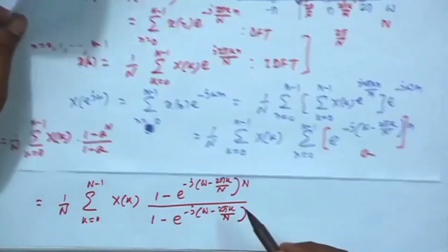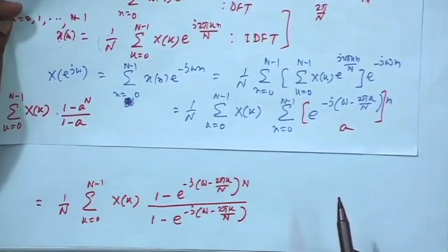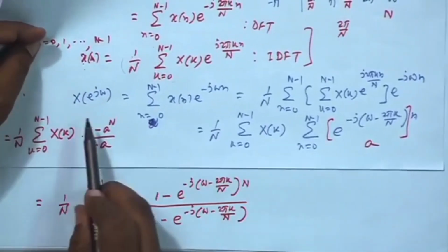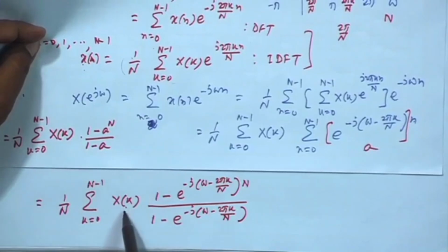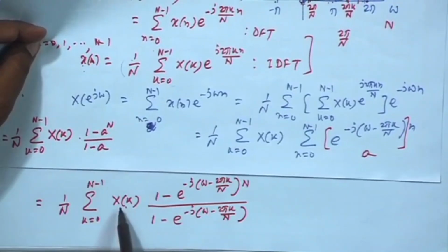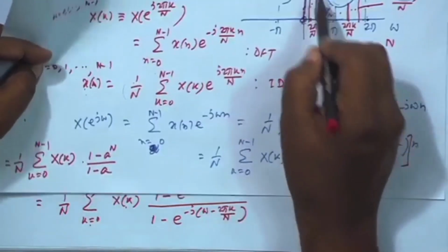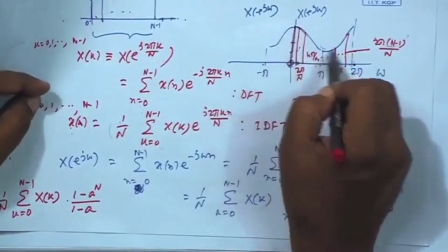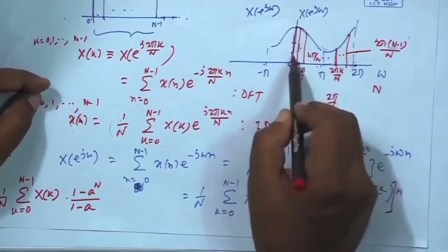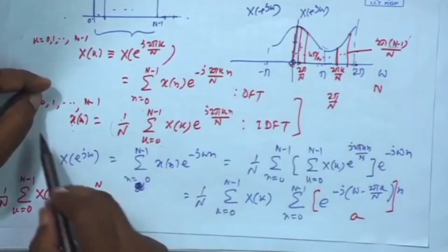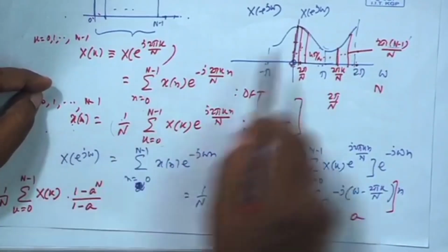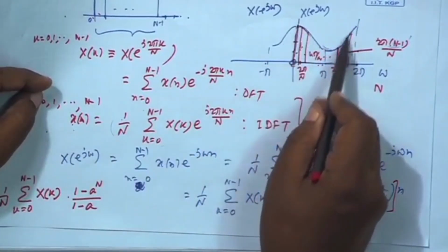Okay, a function of this kind. So, that means DTFT can be obtained from its own samples. After all, what is capital X k? k equal to 0, k equal to 1 and up to k equal to N minus 1 means you are basically taking the whole DTFT itself and sampling it. So, if you know the samples, that is this capital X k, using them you can get back x n, and then therefore, you can get back the DTFT envelope itself.